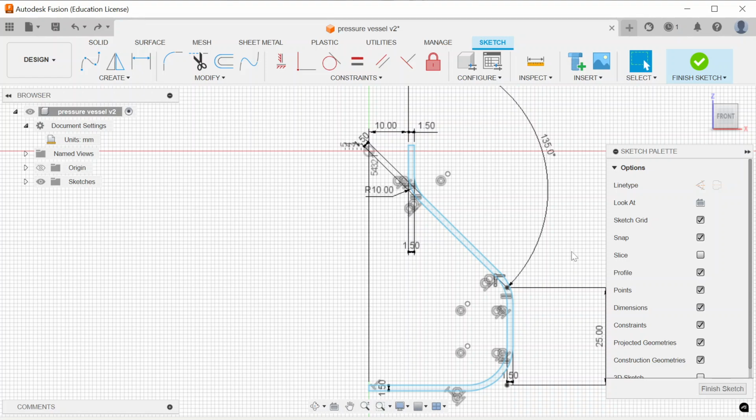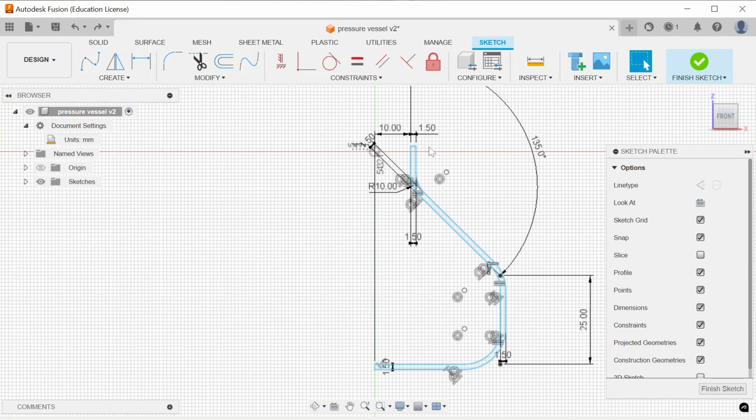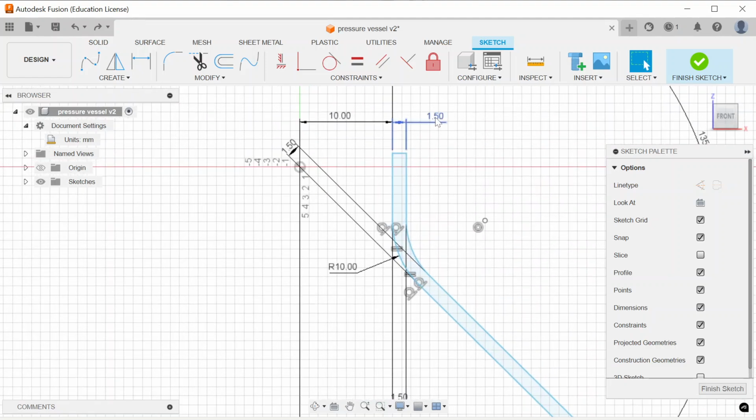And now I want to talk about this sketch. It is not a fully constrained sketch, and I want to have the ability to make some changes to it later, so that is fine. Couple of other important features. It needs to be set relative to the origin. I have set a constraint distance of 10 millimeters from the origin, and my wall thickness on this profile that I've set out is 1.5 millimeters.